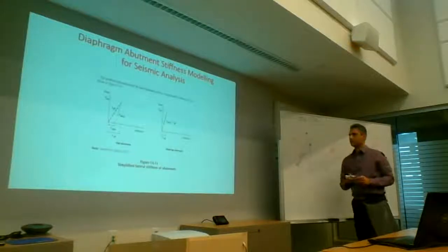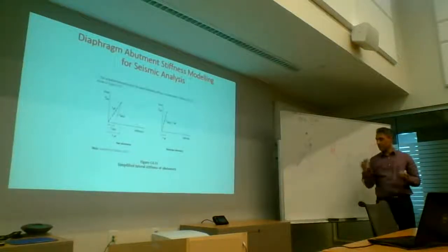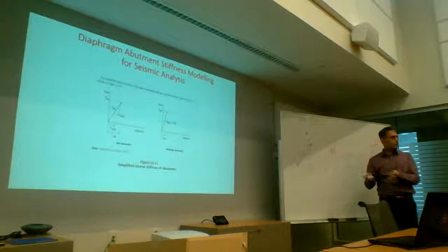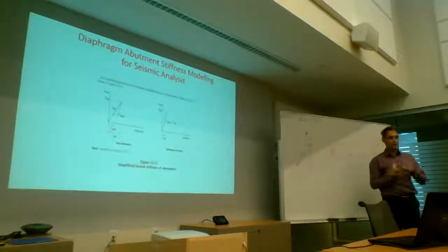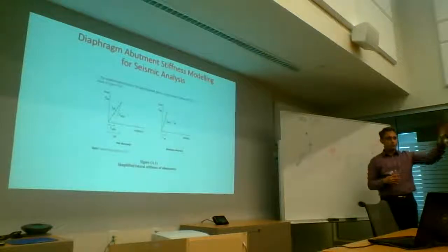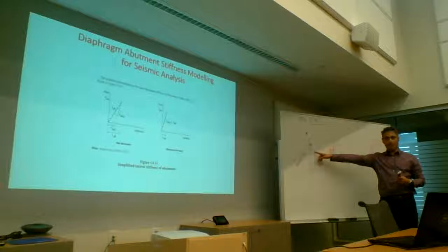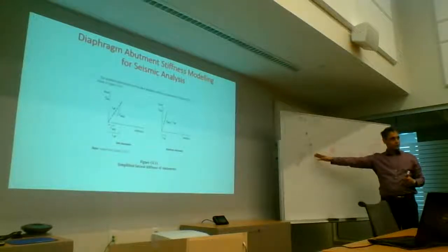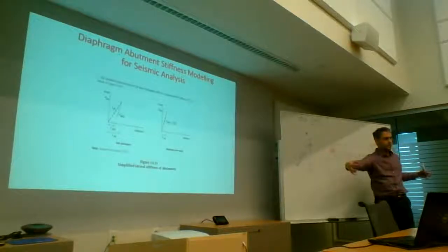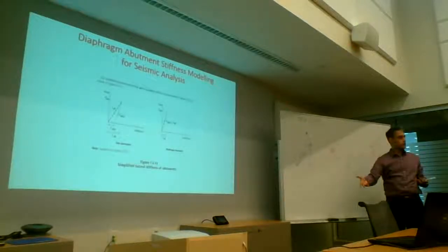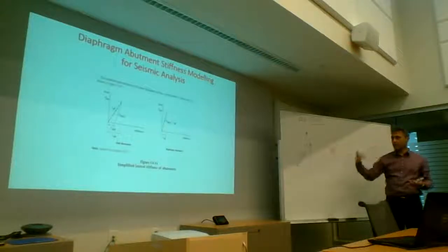This is your delta. So your abutment has moved maybe 30 mils. Can your columns tolerate that, or has it gone beyond the displacement capacity of the column? If it has, you either need to do something with your column now, or you need to go stiffen up and strengthen your abutment, and there are ways of doing it, putting shear keys or putting supplemental piles and attaching it to the original, or you do both. Okay, but you can't just use this.